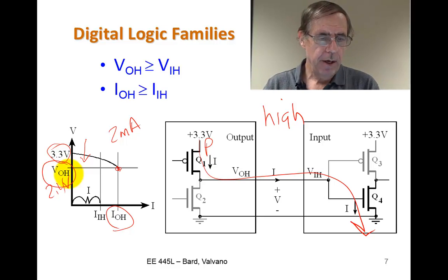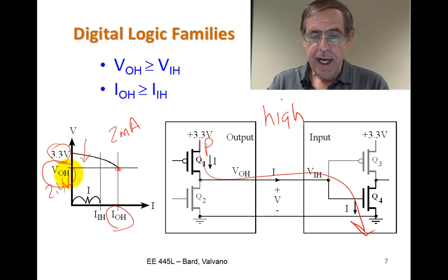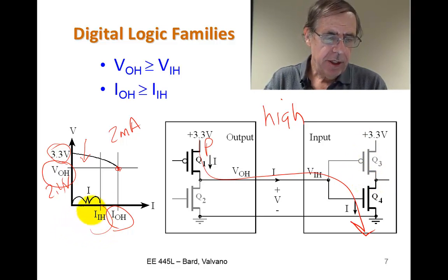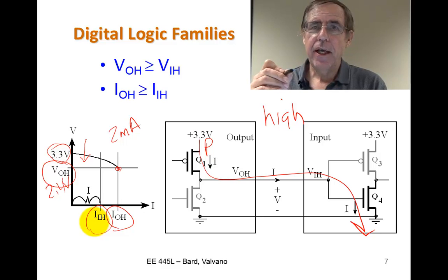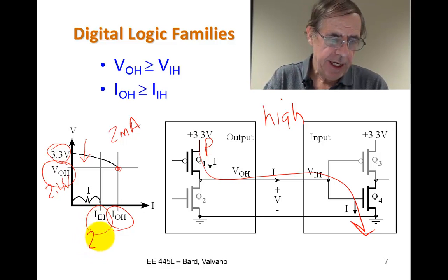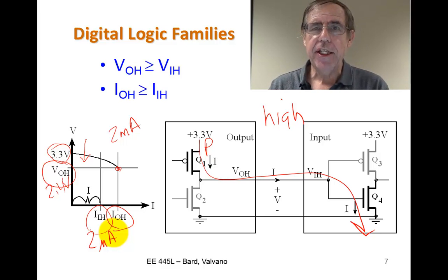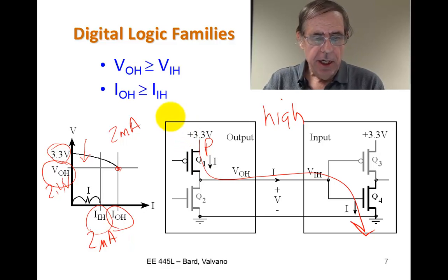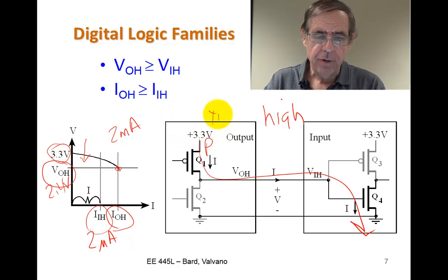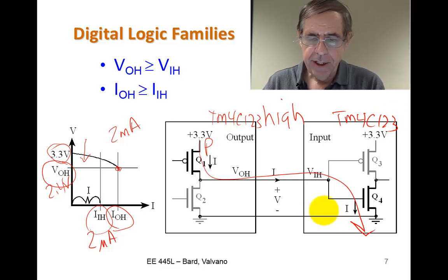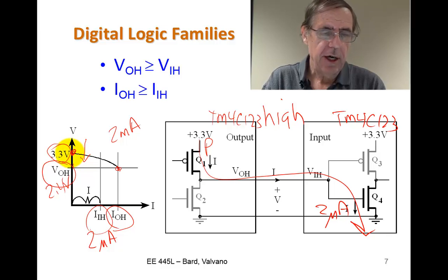Okay. All right. And as we saw last time, as we added up inputs, the current when the input is high, in our case, it's about 2 microamps, is the amount of current that it will actually need to work. And so, as you can see, if we tie one TM4C123 to another TM4C123, this 2 microamp current needed is going to put us way over here on the operating point.